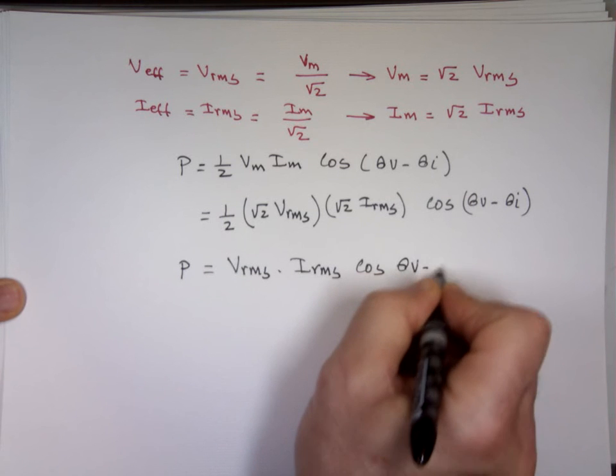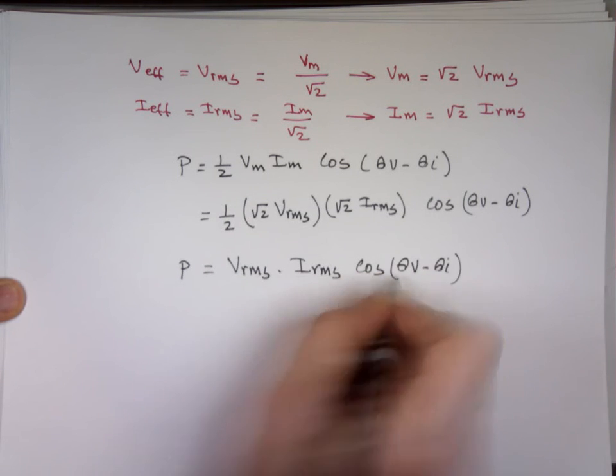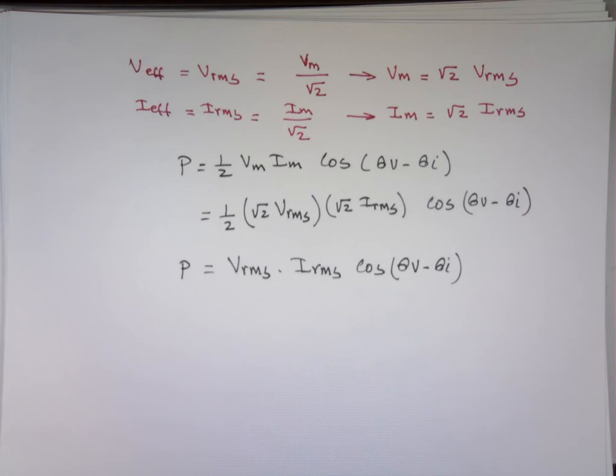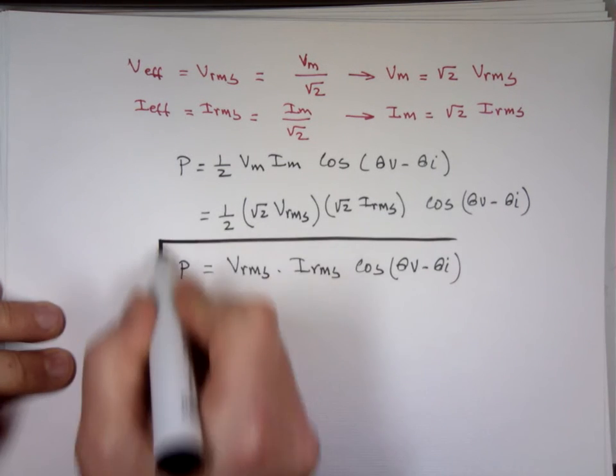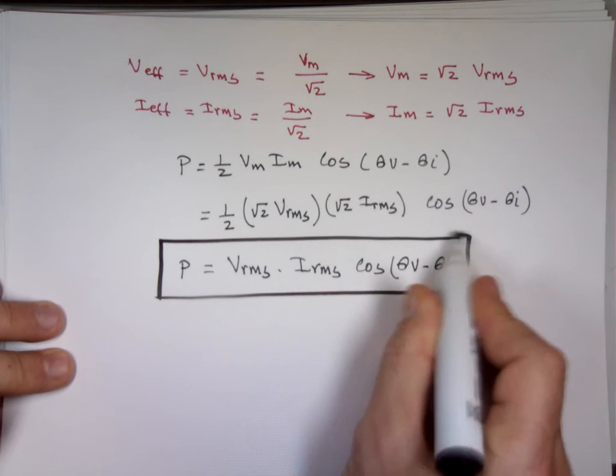So when you're doing these problems, look and see, is the value given to you RMS or is it given to you as a maximum value? If it's RMS, you have to use this equation. If it's the maximum value, you have to use the other equation.